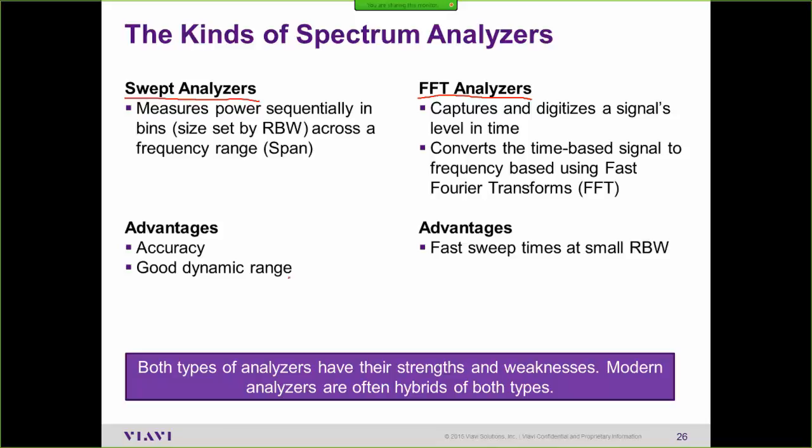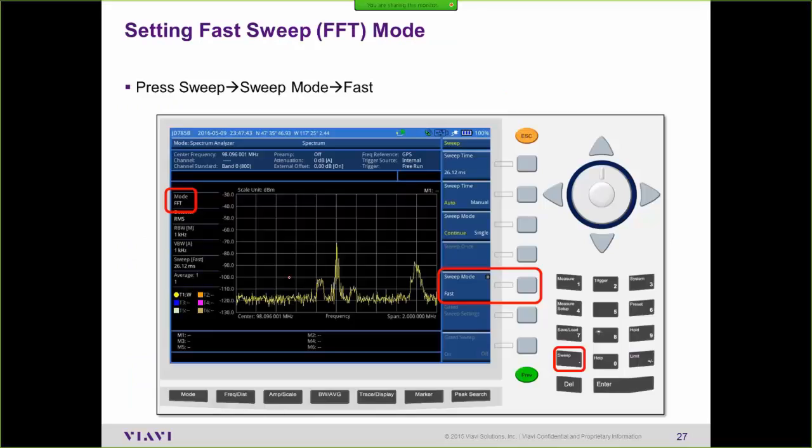Now, if you're making measurements for receivers, receivers have a noise floor threshold, and it's all based on the communication technology's bandwidth. And again, as you measure the spectrum, the amount of noise that's in a particular bin, as we saw on those sample displays, gets lowered when you narrow the RBW because there's less bandwidth and less noise in that particular area. The advantage of lowering the RBW is that as you lower it, the noise in that bin becomes smaller and smaller.